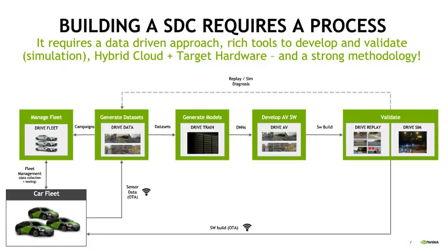Replay is based on collecting real sensor data from the road and replaying it through our AV stack offline in the data center, validating that all the predictions from different signals in our stack do the right things. This typically requires the data to be labeled partially, sometimes less for things that require mostly an analysis of the signals being produced without a check against ground truth.